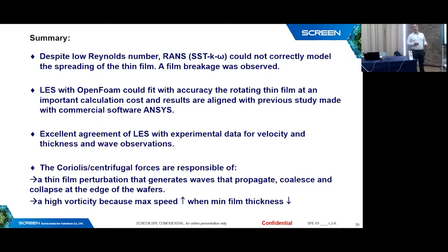We are quite confident about our code because we have data that confirms the simulation, and it also shows that OpenFOAM can do the job of ANSYS. We have excellent agreement with the experimental data for velocity and thickness, and also for the wave pattern we observed on the disk.